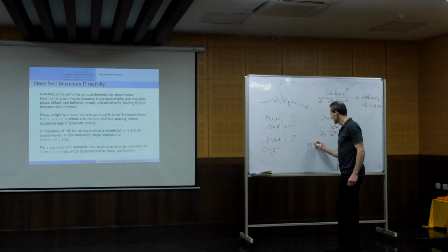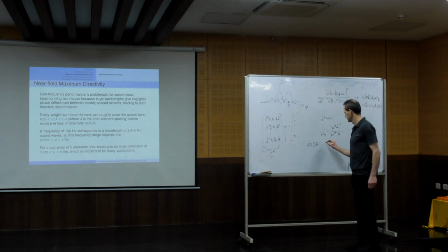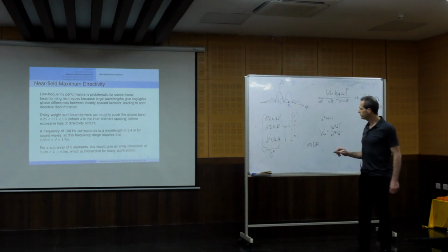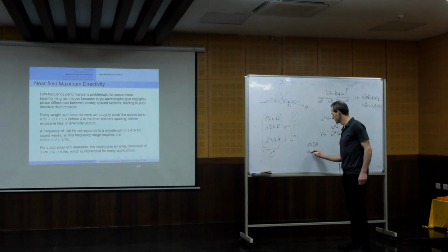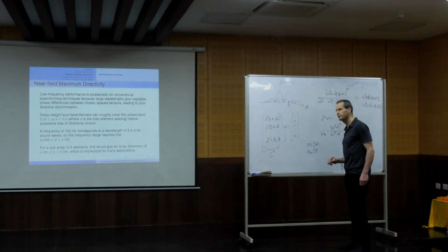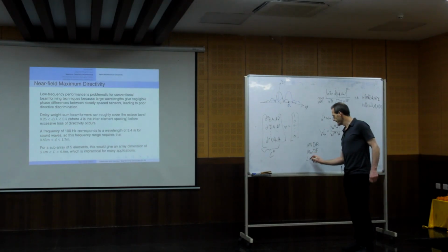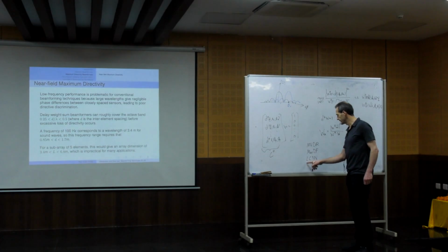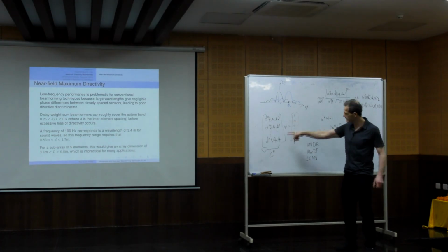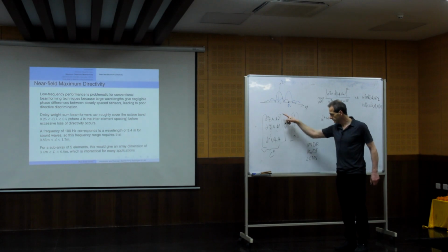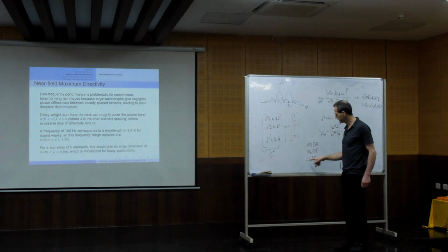Minimum variance distortionless response beamformer, MVDR beamformer. We saw it. We saw maximum directivity factor, max directivity factor beamformer. We saw LCMV, linearly constrained minimum variance with the matrix C. So if we have more than one constraint in one direction, if we have additional linear constraints using this matrix of constraint, we call it linearly constrained minimum variance beamformer.